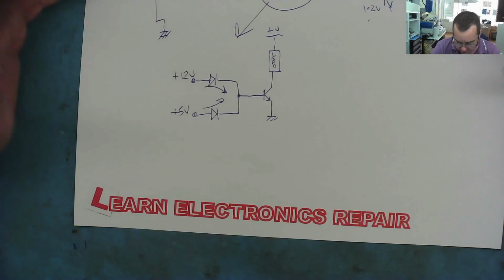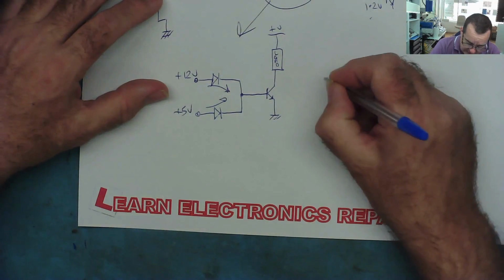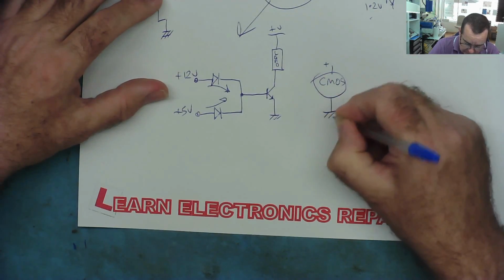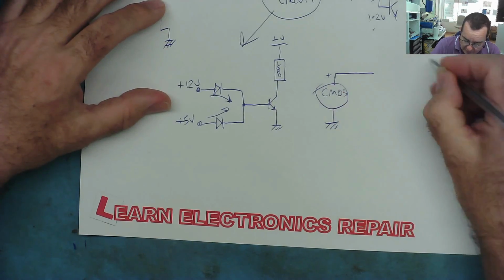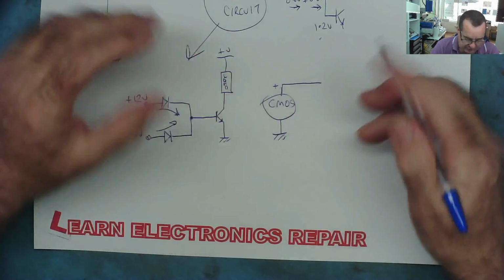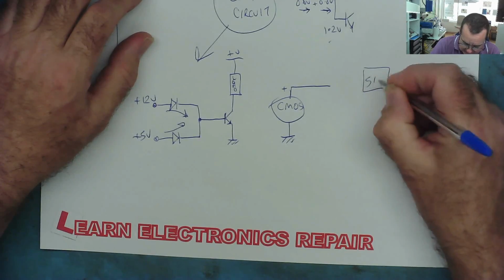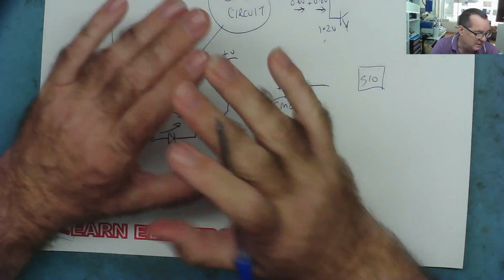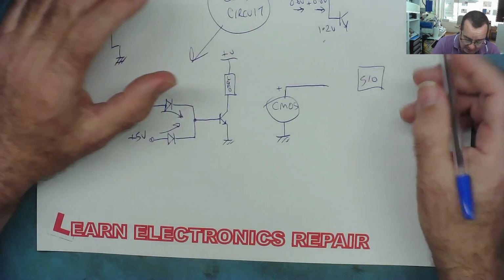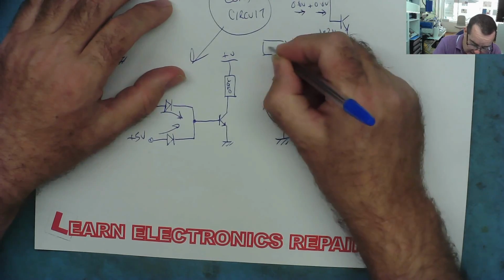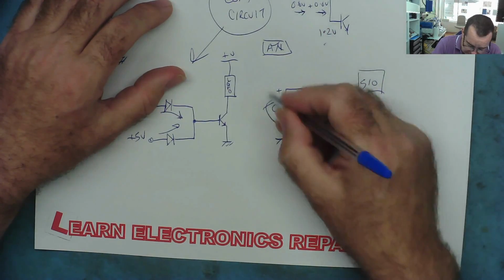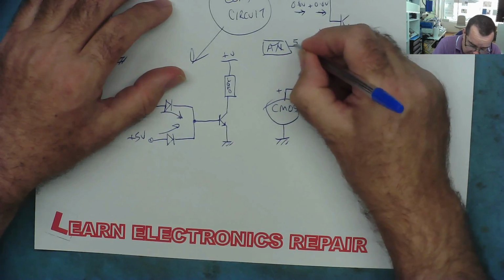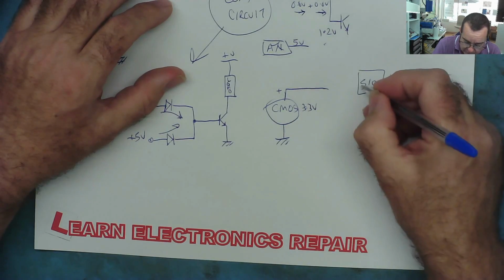Another good example of this, motherboards. So you have a CMOS battery, plus to ground. And this powers the I/O chip, the thing that starts the laptop, called an SIO chip. And also, when you've got your ATX power supply plugged in, you have a standby voltage. This is your ATX. The CMOS battery is about 3.3 volts, and your standby voltage is 5 volts on your power supply. And you want both to power this chip.